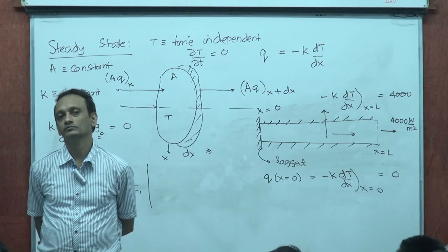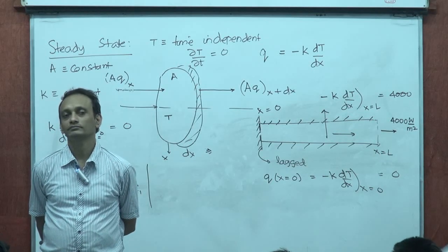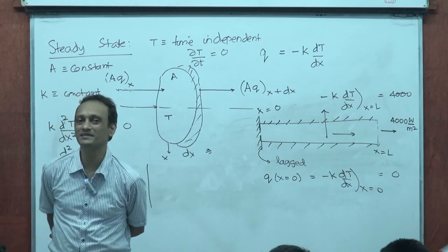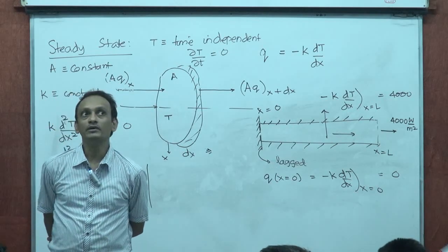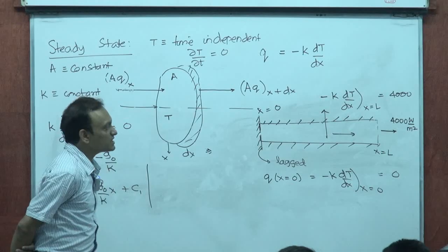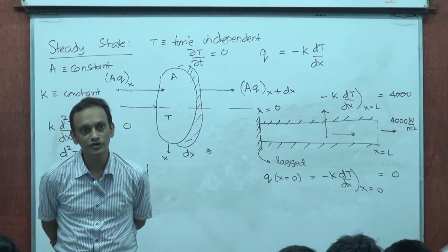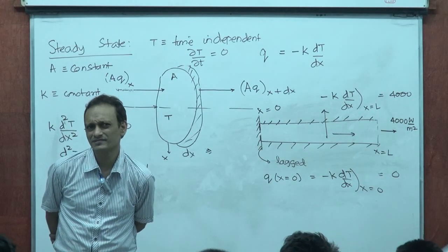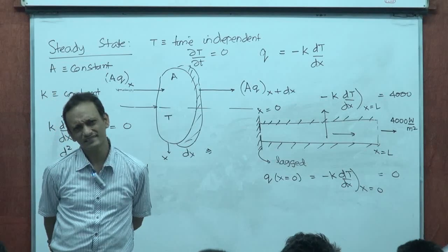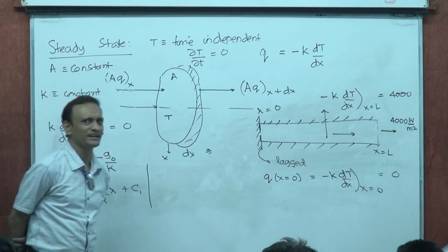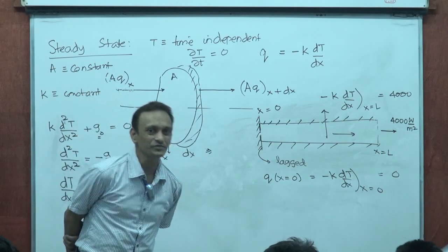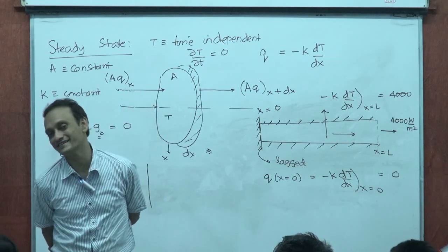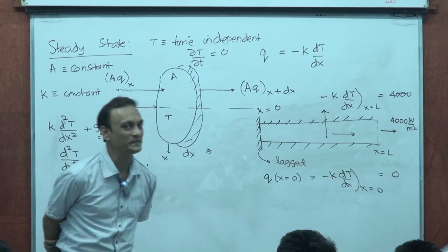Find out the equation for x, then with y. No, you can't superimpose that way. I mean, in that case, it's not linear, isn't it? Do you realize that the expressions are not linear? You could superimpose if they were linear, right? But you can't superimpose stuff like that, in the sense that you assume heat flowing in one direction and not in the other, then the other direction and not this one, and you add them up. You can't do that, right?